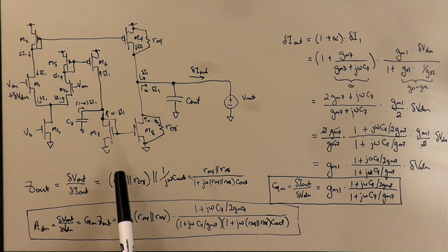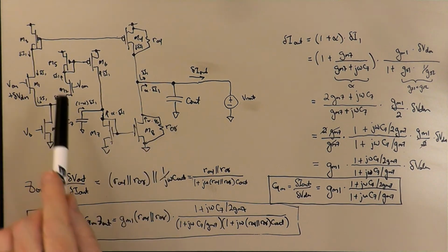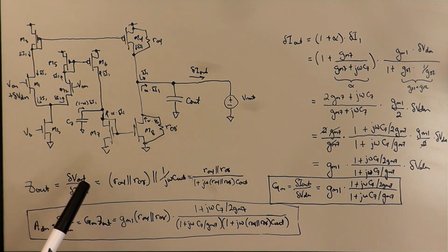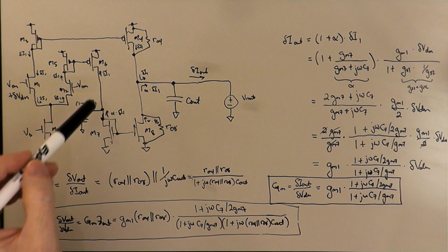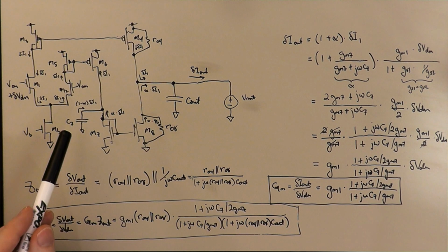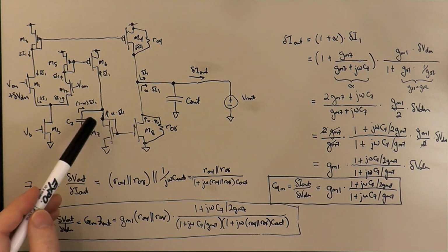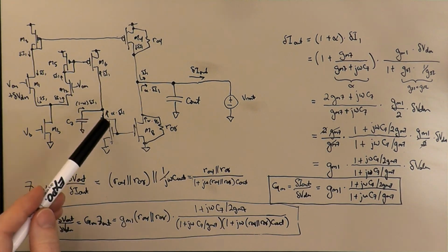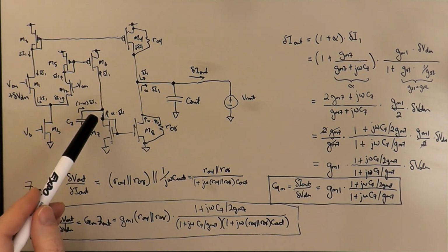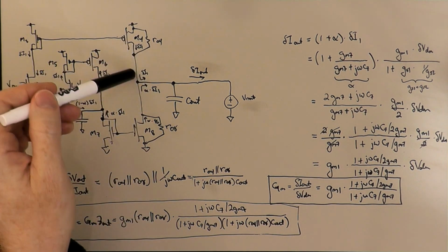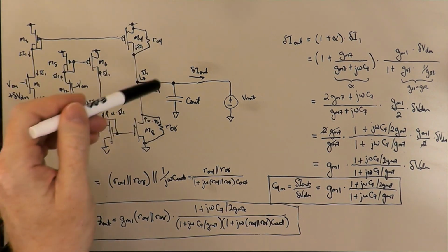And so we can use some common sense in terms of, how big are these capacitors likely to be, and if we have the actual physical design of this amplifier circuit down at the transistor level, we can estimate some of these capacitances, and we can say, well, these smaller capacitances probably won't kick in till higher frequencies, and we can estimate what are going to be the various low frequency impedances or resistances of these various nodes, and say things like, well, this output has got two drains, and so the early effect resistances are going to be sort of the dominant component there.